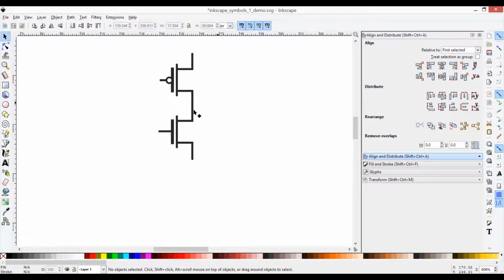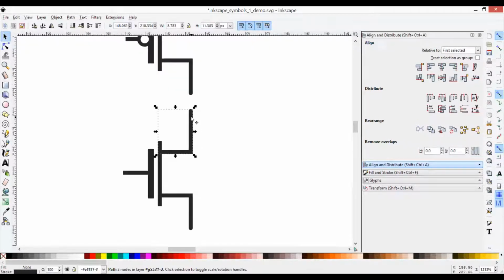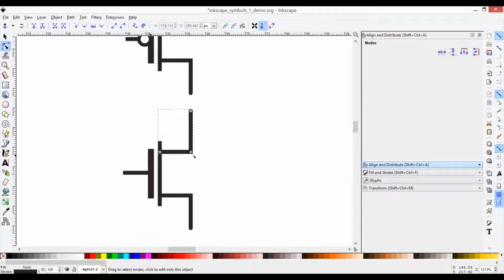The way that it looks now, it looks like they're connected, but they're not actually connected. They're just perfectly overlapping. If you actually want to connect them, I'll double click on this guy to descend. And if I double click on this shape, I'll enter the vertex editing mode. So I can see the vertexes of the shape, and I can click and drag them. I can add a new vertex by double clicking in the line. I can delete a vertex.